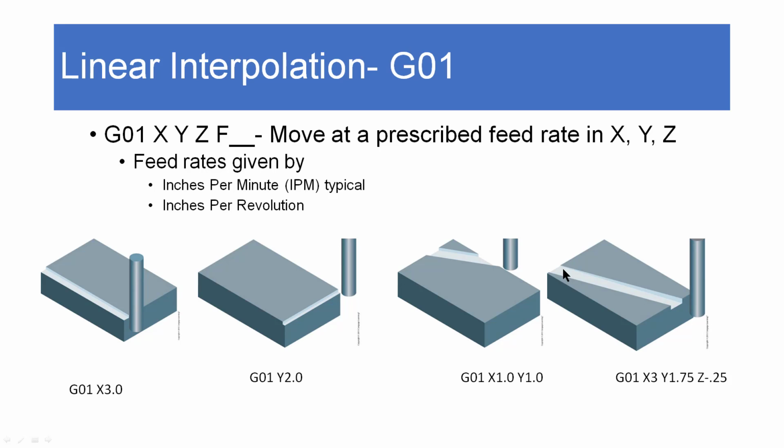And here's in three dimensions. I'm going X3, Y1.75, and I'm reducing or cutting down in depth to Z.25. So I can move in three dimensions with that command. Very handy. We'll use that all the time.